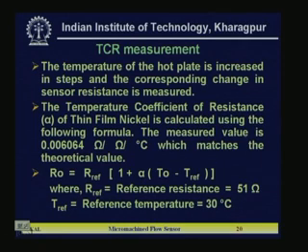So, the alpha measured value is obtained as 0.006064 per degree centigrade, which matches the theoretical value. The theoretical value is nearly 0.0064 or 67 something like that. Up to the third order it is matching properly. A slight deviation is there because, whatever heating I am giving, exact measurement of the temperature of the film is very difficult, because a lot of heat is lost due to the ambient temperature difference with the heater temperature. If the heater temperature is large compared to the ambient, there will be heat loss due to radiation, and exact measurement of the temperature of the film is not possible.